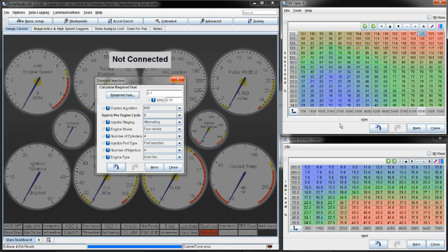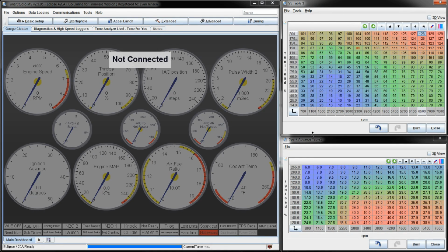Some guys will go with 1000cc injectors, which is fine, or even 2000 on some of the crazy builds. But go back and watch my high versus low impedance injector video, and I'll talk a little bit about why you don't want to just go for 1000 or 2000 necessarily. A lot of the modern injectors are working pretty well, I think. I don't have any personal experience with them, but from what I've read about it, the modern injectors you can actually idle with a 1000cc injector, but I guess back in the olden days maybe they weren't as good,